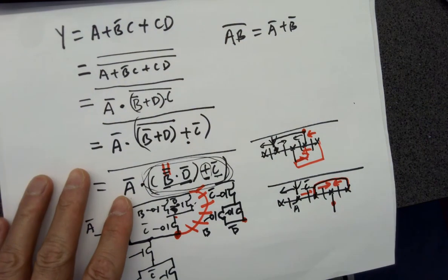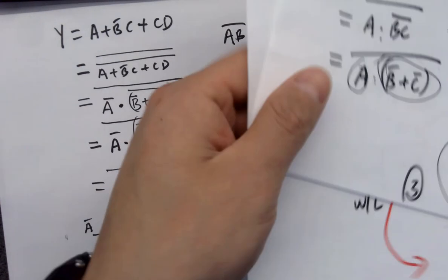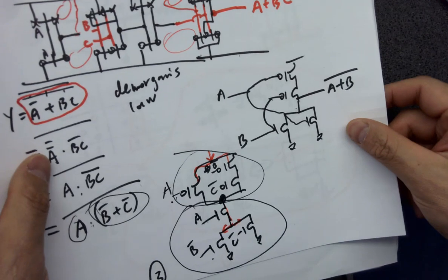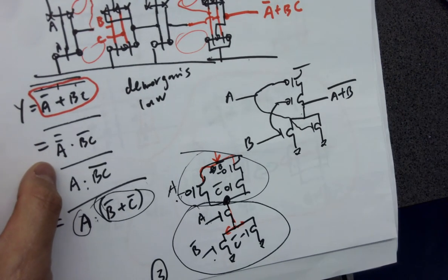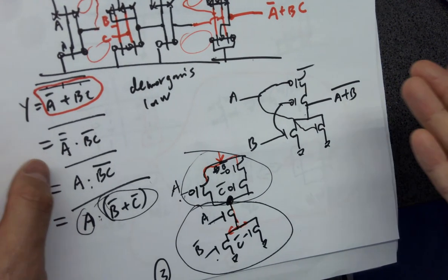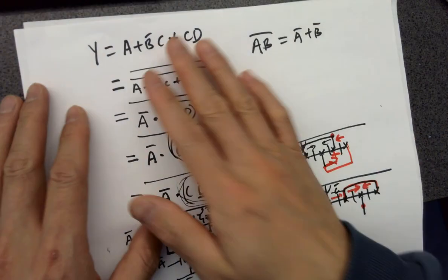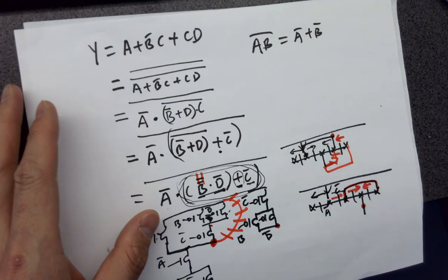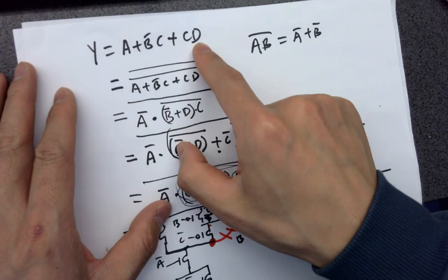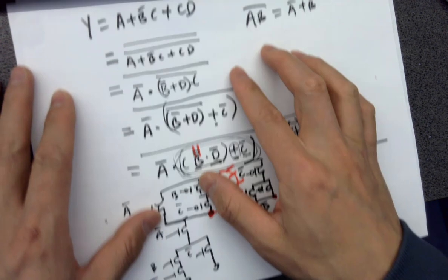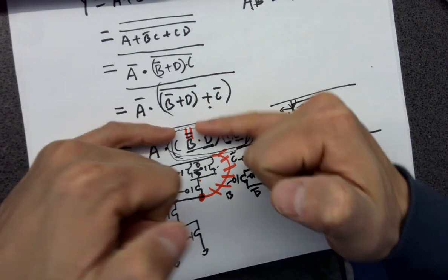If you directly draw a circuit using the PMOSes and NMOSes, it's always getting inverted because of that. And we don't have to dig too deep into that theory because it happens. It's already what's happening. Okay, so in that case, we can design it backwards. If we see a logic like this, we want to form a logic expression which has a bar on the top.